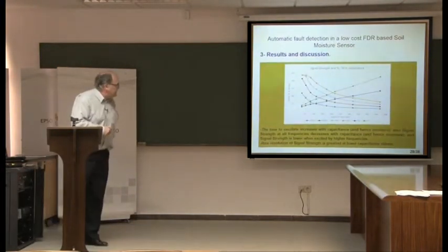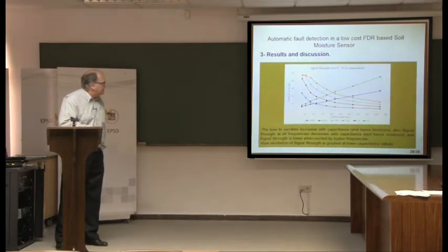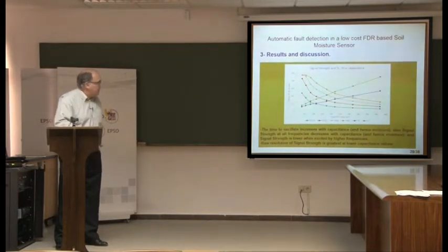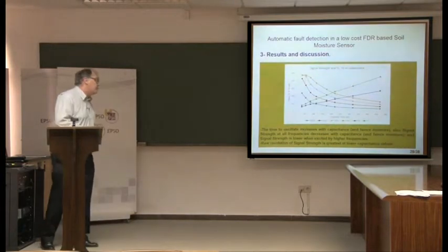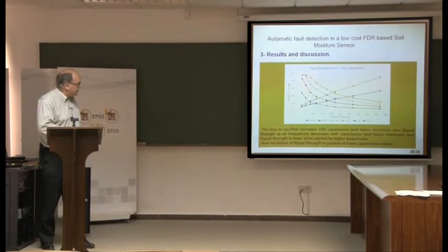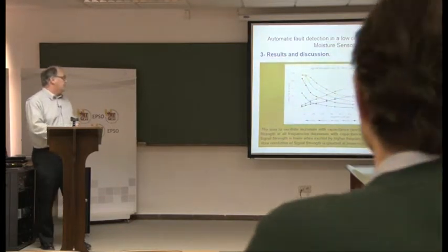If we look at the signal strength readings that we got using the 4 different frequencies we've mentioned, so this one here, for example, is the 62 kilohertz, 83, 125 and 250 kilohertz, you can see that these signals drop when, instead of the probe, we put a known capacitance as the input to the device. So you can see that as the capacitance increases, so this value drops. In contrast, as you would expect, as the capacitance increases, the time to charge and the time to discharge increase linearly.